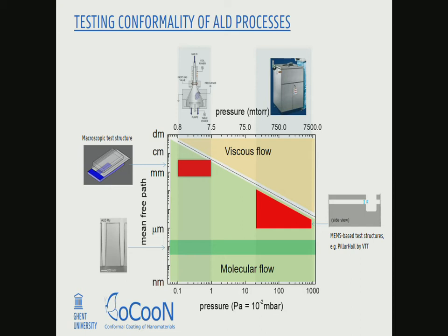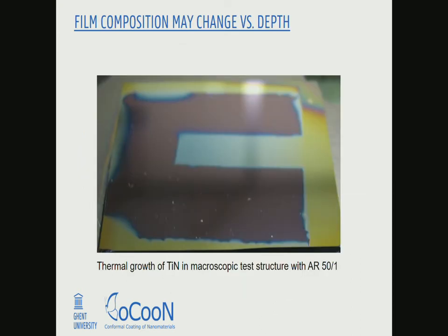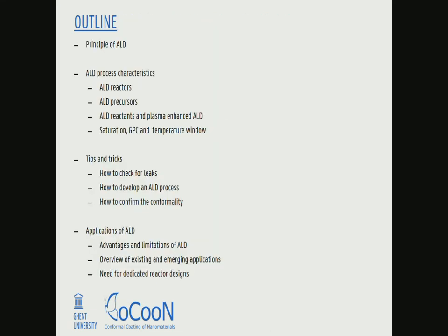So for testing conformality, it's really useful, and often for ALD processes, especially for instance for plasma-enhanced ALD processes, it's important to verify conformality, because it's not because you're growing in an ALD process, and it's not because you think that you're doing ALD, that de facto it will be conformal. It really makes sense to verify.